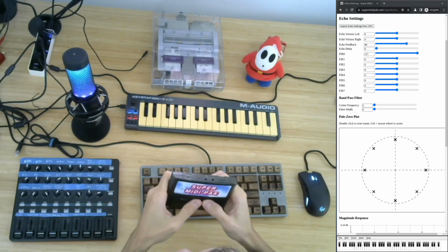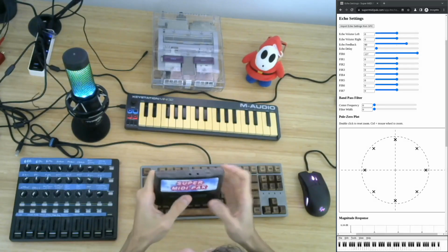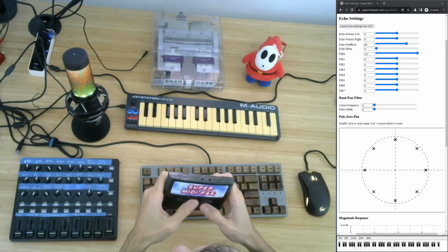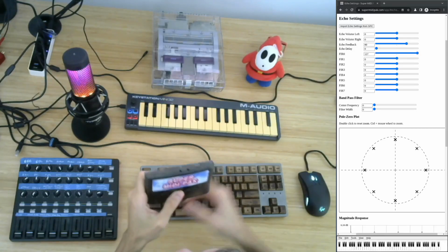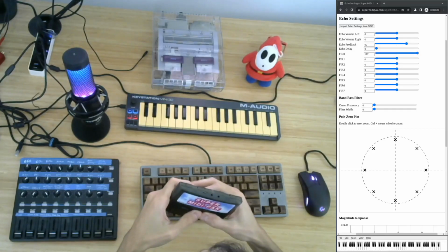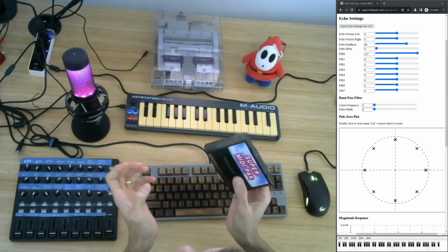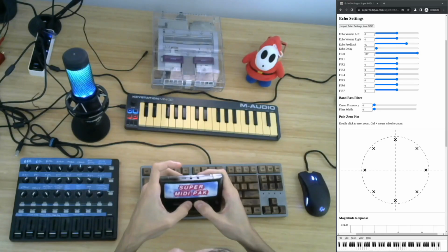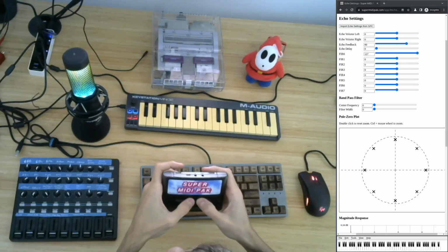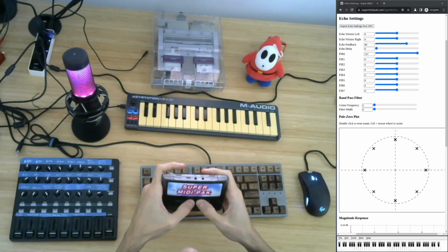Recently I learned a bit about digital signal processing, or DSP, for another project, and I realized I could apply that knowledge to build a tool that makes it easy to design certain types of effects using the integrated FIR filter. These are effects like low pass, band pass, and high pass filtering. Doing these types of effects in real time on the audio hardware enables doing things with audio that were previously impractical or impossible to do on the SNES.